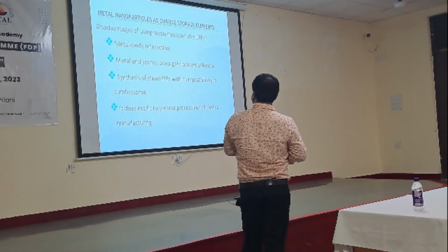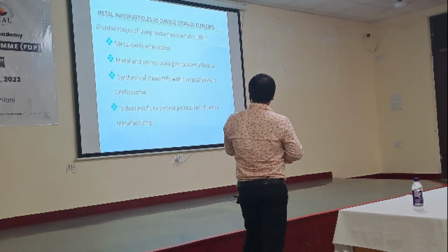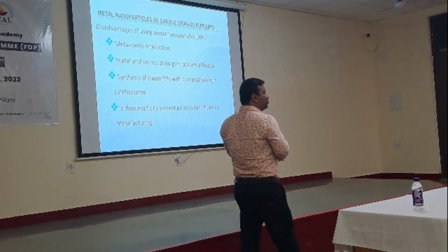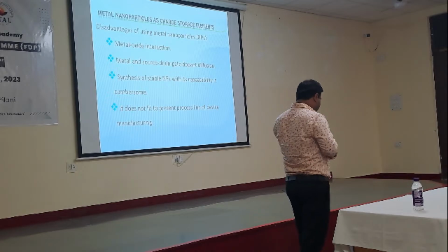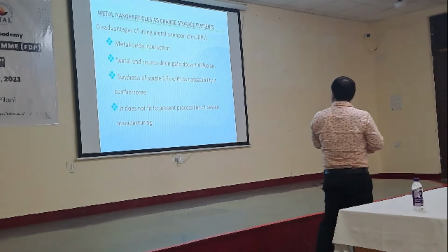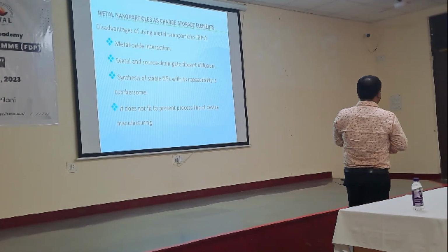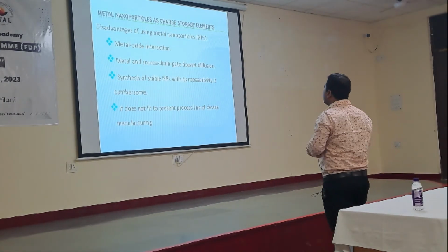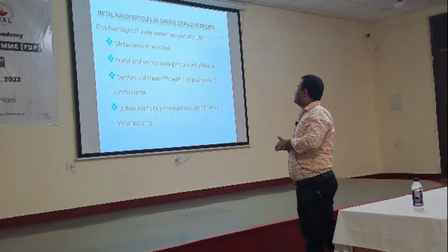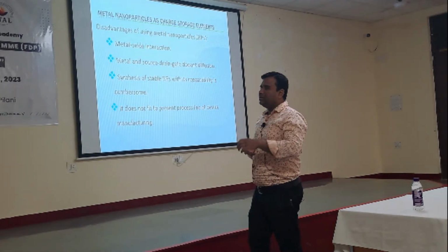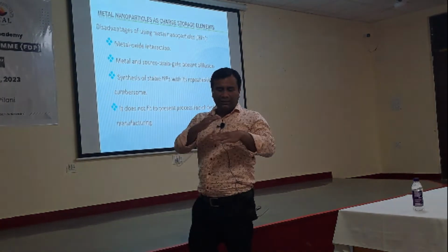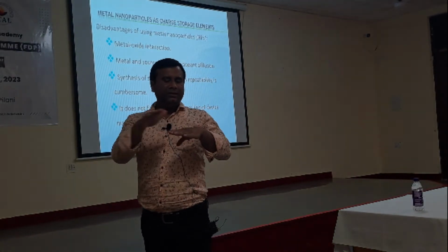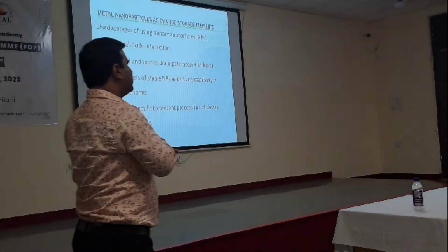Next. Now, as I just said earlier, previously reported in the literature, people are using metallic nanoparticles, but instead of using metallic nanoparticles, I have replaced them with indium arsenide quantum dots. Why? Because if we use metallic nanoparticles, then with a metal oxide, your metal may react with the oxide material.